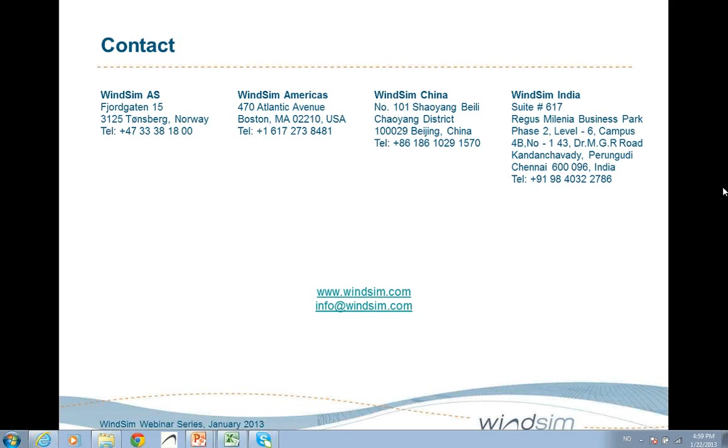Then we have a question about bad wind measurement data. Of course, bad wind measurement data we cannot do anything about in WindSim. Here I would also refer you to Windographer, because Windographer is a really nice tool to clean the wind measurement data before you give it to WindSim, because in WindSim we really assume that you only have cleaned data inside the simulation.